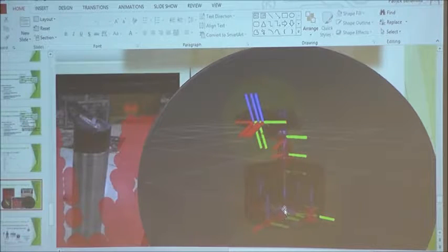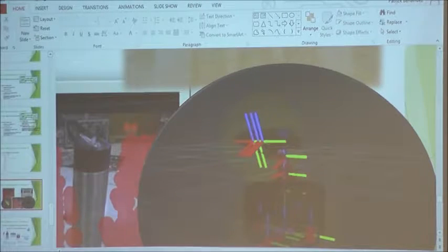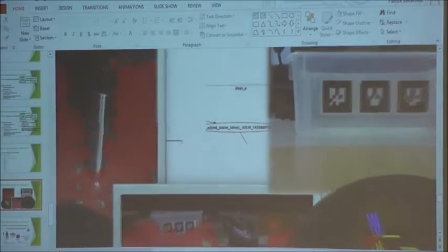What you're going to have here is the base link, and that base link goes up to the different links that are measured relative to that one. And you're going to have some sort of angular changes here and there. In this case, it's the camera that's looking down a little bit. I have it to where I can get IMU data and adjust the level of the camera, which is very important. When you look at the kind of data that I'm working with, if I zoom out a little bit, I can show you that.